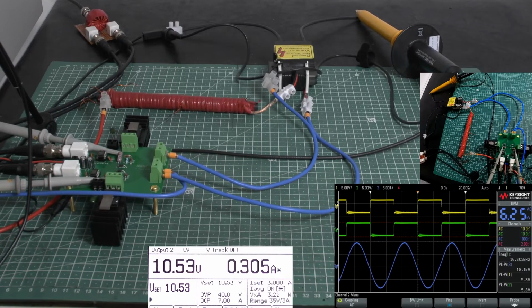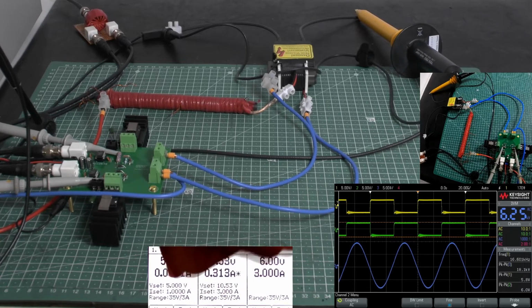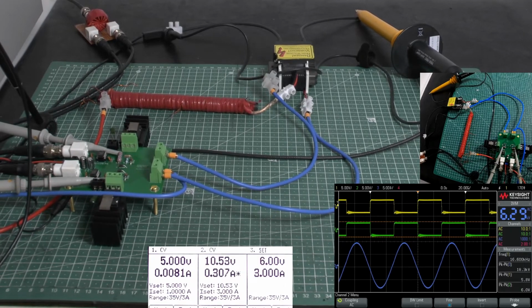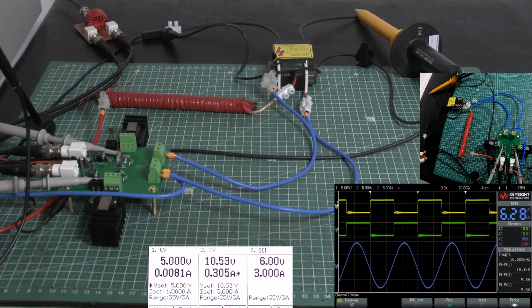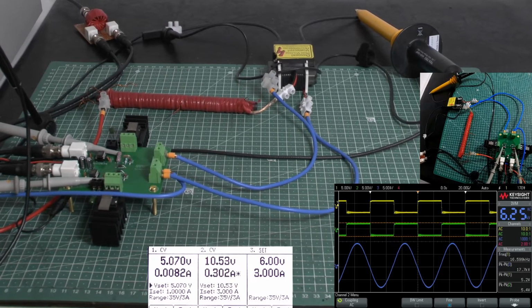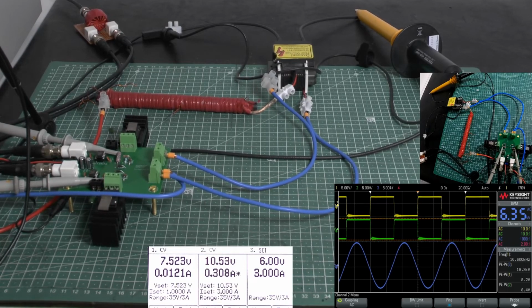And you can see here, we're measuring only 5.8 volt. And I put in currently, let me show you that, I'm putting in 5 volt only. So that is a slightly higher offset. So if we increase that here, let's say we go to 8 volt, which helps us a little bit with the transition.